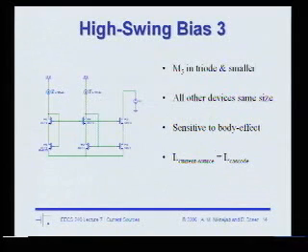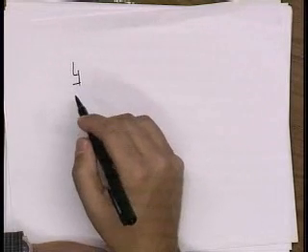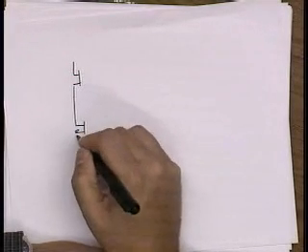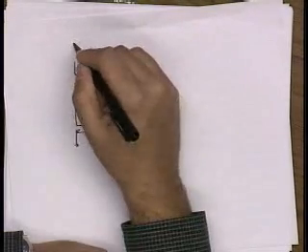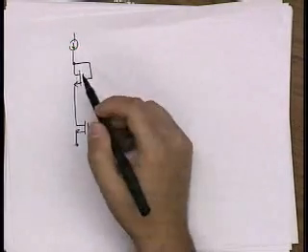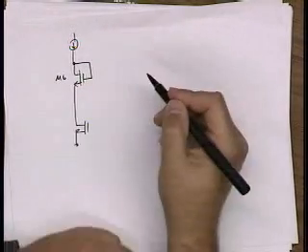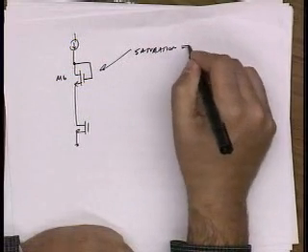All right, and let's look at just one more device, and from there we can start moving faster because these are all variations on the same theme. In this version, we're actually going to generate our overdrive voltage with the device in triode region. And the way you do that is you have one device which is diode connected. So for sure this top device, M6, is in saturation. By definition, it's diode connected.